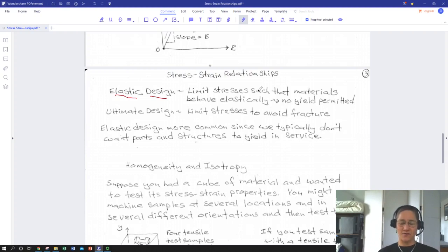And that takes care of the fact that we are never quite sure exactly if the piece of material that we are buying and designing with will in fact have the rated strength. Typically manufacturers sell according to what's average. Woe betide the person who gets the thing that's 3 sigma to the weak end. Your roof's going to break. So we use safety factors to allow for the fact that materials are not consistent, and we can't test 100% or we would have nothing to sell.